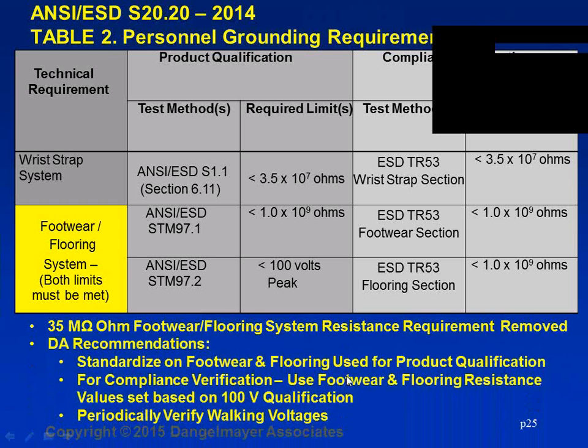And Ted, you'll have to hit the next one. Our recommendations are that you standardize on the footwear and the flooring that you use. So whatever you do to qualify the floor, the compliance verification should use the same footwear and the same floor. There are too many chances for differences to occur if you change footwear and flooring, and we'll show you an example of that in a moment.